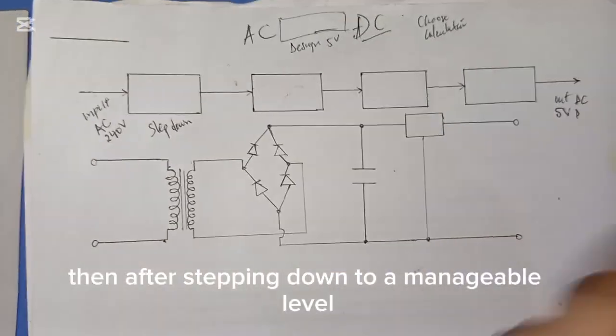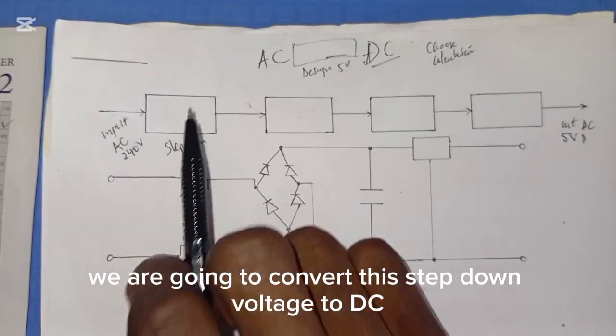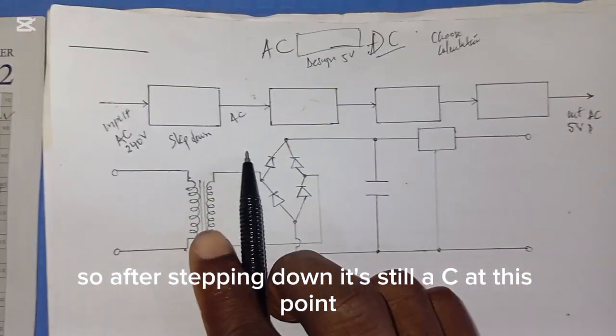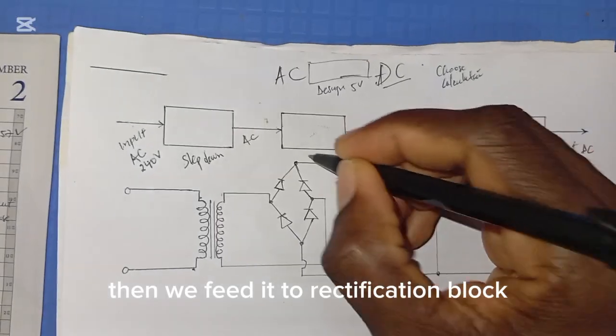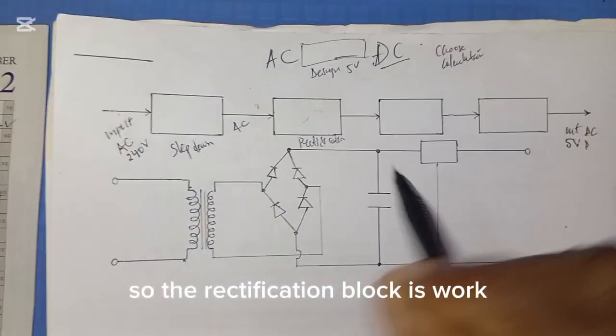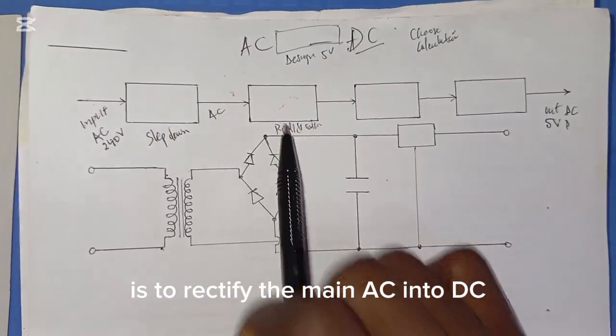Then after stepping down to a manageable level, we are going to convert this stepped-down voltage to DC. After stepping down, it's still AC at this point. Then we feed it to the rectification block. The rectification block's work is to rectify the main AC into DC.